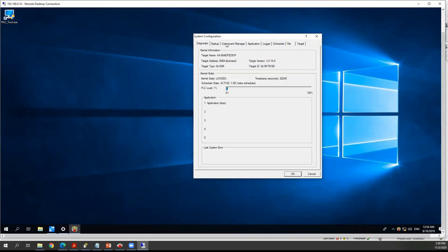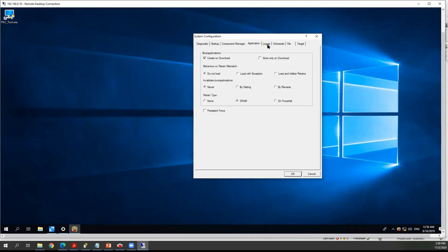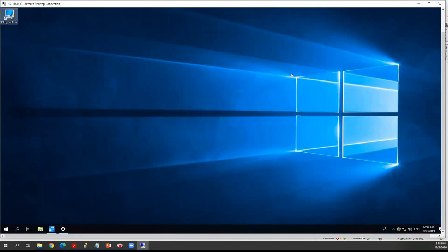Okay, so this is the interface to get some information about the CODESYS runtime. What we are talking about here is that there are two types: the CODESYS development environment and the runtime. The development environment is the part where we write our code, and the runtime is the kind of root of the PLC, so it is executing your program inside.